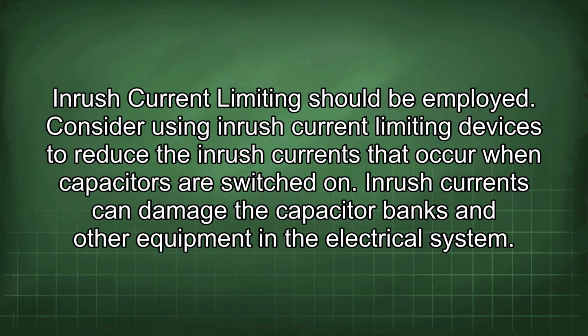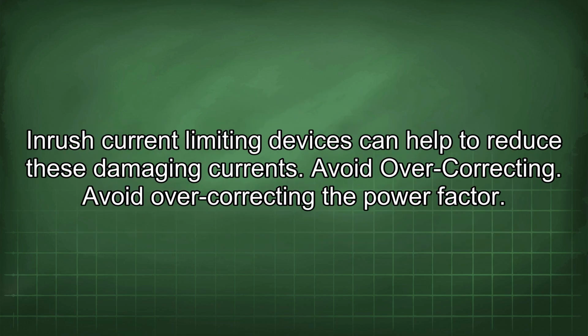Inrush current limiting should be employed. Consider using inrush current limiting devices to reduce the inrush currents that occur when capacitors are switched on. Inrush currents can damage the capacitor banks and other equipment in the electrical system. Inrush current limiting devices can help to reduce these damaging currents.